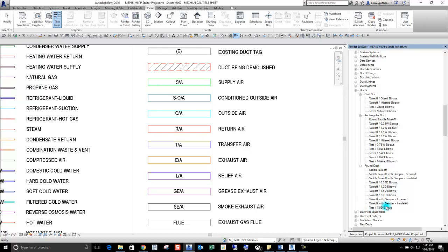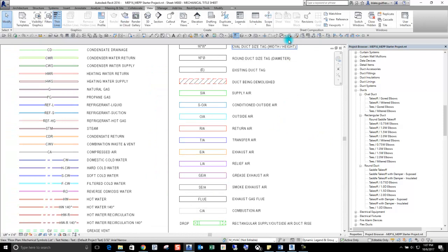A lot of these are set up as takeoffs, but there's something to be said about that, because right now the takeoffs don't calculate the static pressure drop coefficient correctly, which is a known bug that's been discussed by many people in Revit. So if you want more accurate pressure drop calculations without having to input a lot of manual values, you should use T's in that situation. We can talk more about that as we go on. So let's go to a couple plans and see what some of these duct types look like.